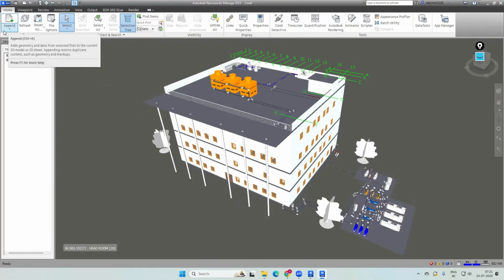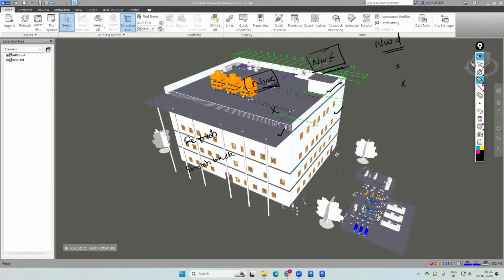No, this is like, Navisworks NWF files will be acting like external references. Whenever in AutoCAD we are using external references, no, XREF, whenever changes are happening parallelly in the AutoCAD XREF file, it will be reflected in our files as well. From the MEP point of view, in our classes we have studied, we will be attaching the architecture file like an XREF only.